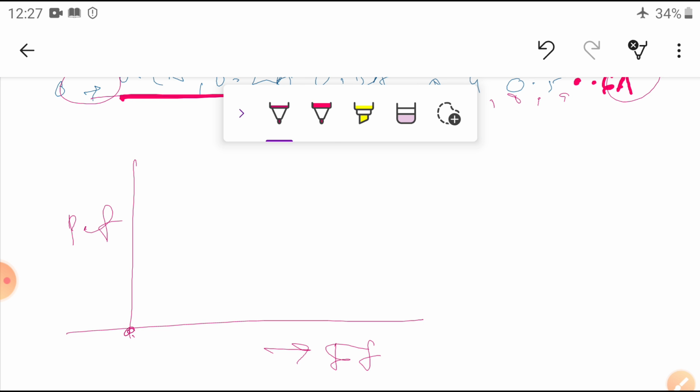Initially, whenever the field current is equal to 0, the power factor is a small value. If this is increased further, the power factor increases. If the field current increases, the power factor also increases. So it increases, and the power factor also increases up to some excitation. As the field current, the excitation to the rotor, increases, the current taken from the supply becomes leading, and the power factor also increases.